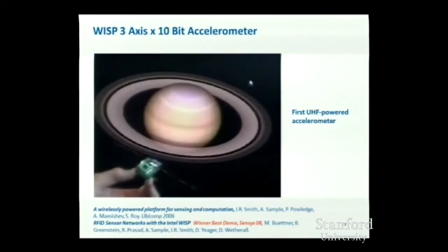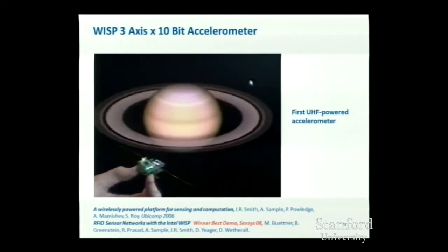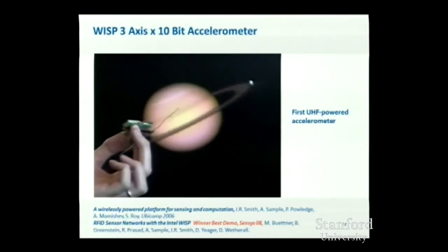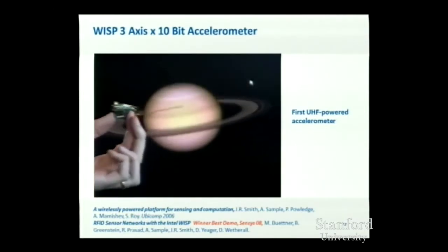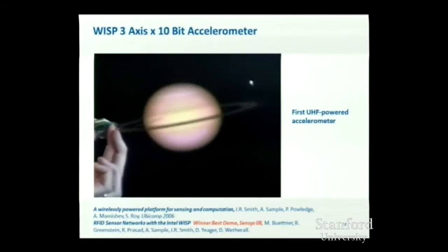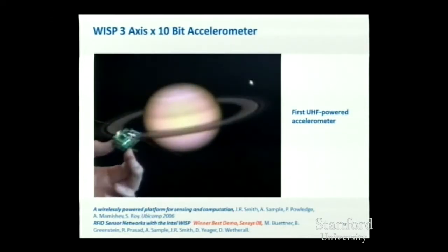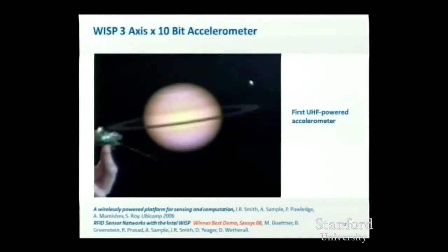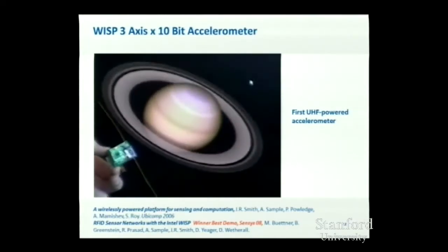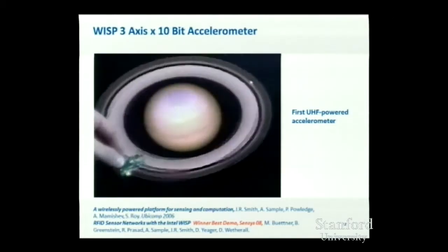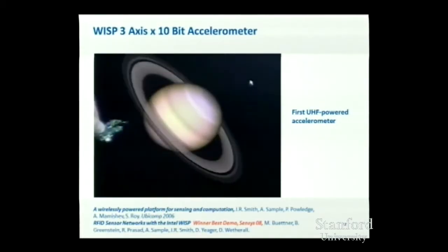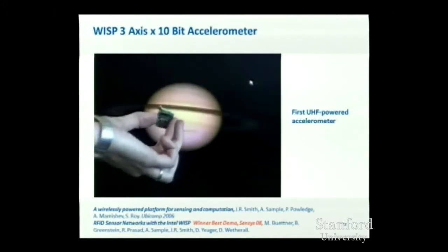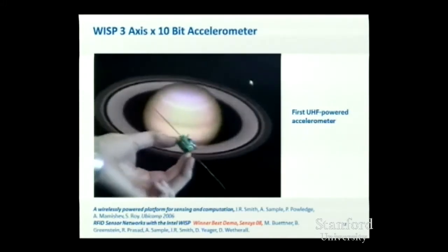So now as I tilt this stack of boards back and forth, the accelerometer is seeing gravity showing up on the 3 different channels, the X, Y, and Z channel of the accelerometer. The microcontroller is reading the values, the analog voltages that are coming out of that accelerometer. It's encoding them, computing a CRC, and doing this backscatter communication to encode the tilt for the reader, which is then drawing this picture. So you can think of this as a kind of input device. And in fact, this accelerometer is the same thing that's in the Wii game controller.